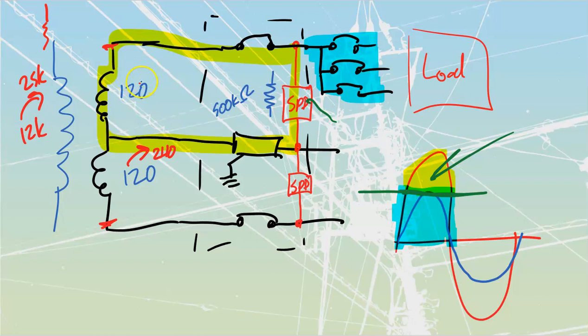When I go to a higher value of voltage, based upon the construction of this, I can set it to trigger at X value of voltage, 170 volts or something like that. If it hits 240 volts, what will actually happen is its resistance will have dropped. And in that case, the resistance might be down to like 8 ohms or something like that. It's a really drastic drop when these things go into conduction.